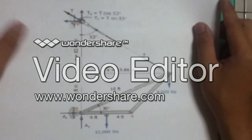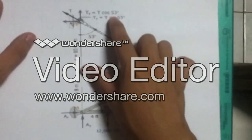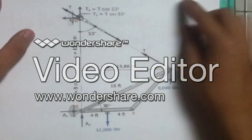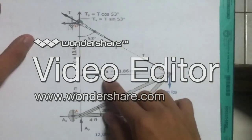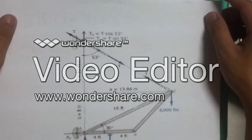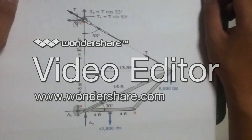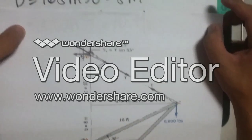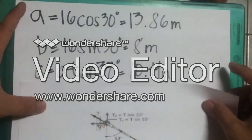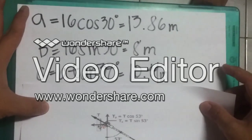For the first step, we assume that Ty is equal to T cosine 53 degrees, Tx is equal to T sine 53 degrees, and to find the lengths A, B, and C, we derive the formula A is equal to 16 cosine 30 degrees, or 13.86 meters. B is equal to 16 sine 30 degrees, equal to 8 meters, and C is equal to A times tan 37 degrees, or 10.44 meters.